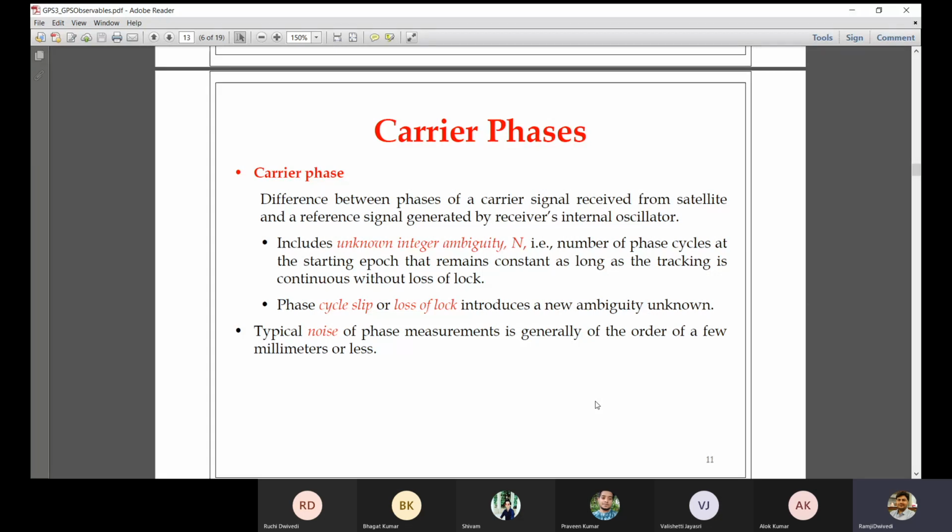So with the reading of that signal, it initially knows, with the help of the identification number which is available in the navigation message, which CA code it needs to open. Then it opens the CA code, okay, and it tries to correlate with the internal replica of the same signal. Clear? So in the meantime, it does so in backend processing, this correlation for identification of the time of